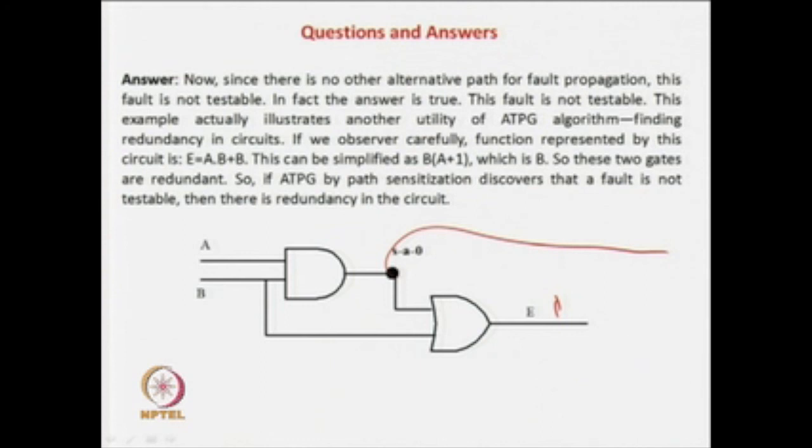Sometimes it may happen that there is only one fan out, as in this case. So, in one iteration we stopped and found that the fault cannot be detected. But in a general case there may be a large number of alternative paths, and for none of them the answer is successful. So, you always have to go for sensitize, propagate, justify, failure; sensitize, propagate, justify, failure. We keep on doing it for some 100th option possible, and then we find out that the fault is non-detectable, and our algorithm has taken a lot of time and we are in a bad situation.